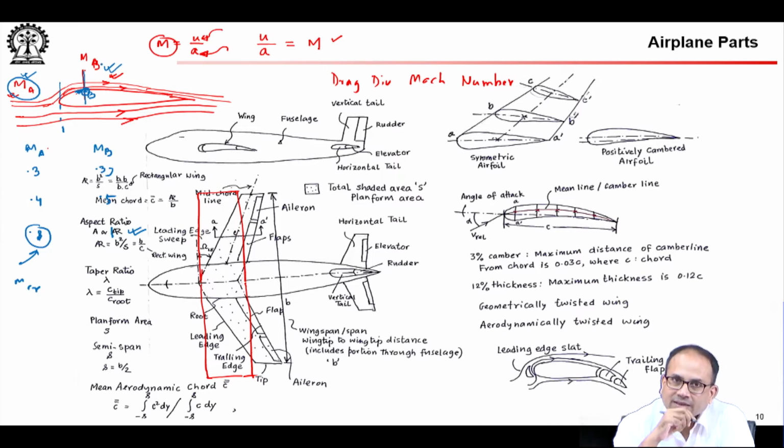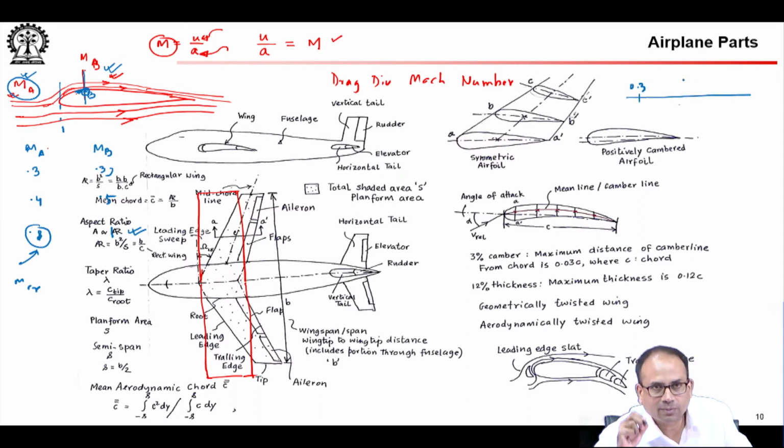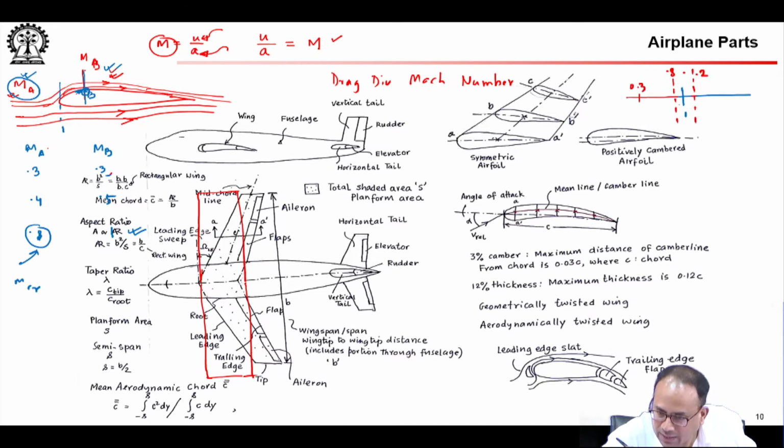So, this is that transonic thing that we showed you in one of the slides before, that is near Mach 1. In the Mach number line, if you remember, we indicated an important Mach number 0.3 and said some compressibility effect shows up above this. Then we did Mach 1, of course, the sonic subsonic boundary, but we also said that around Mach 1 you have this window of Mach number ranging from 0.8 all the way to 1.2, again loosely defined.